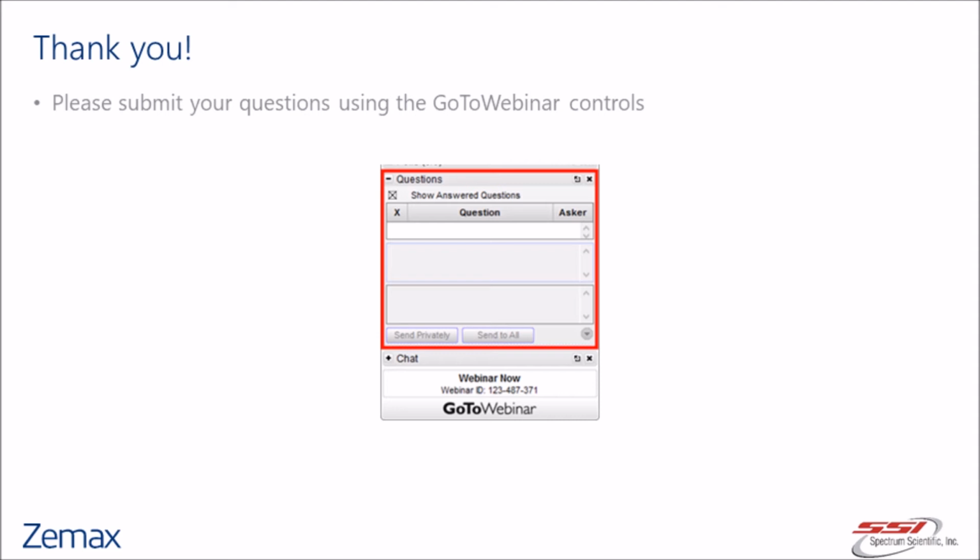Grant, I think this one is for you. If you are only interested in 1 to 2 freeform parts, is the replication manufacturing method still appropriate? That's a good question, and it actually doesn't make sense if you just need 1 or 2 parts, because to do the replication process, we usually order 1, 2, or 3 masters to begin with. So for prototyping purposes, in small quantities, just have them directly manufactured. When you get into higher quantities, in the dozens, it's more cost effective to use the replication process.